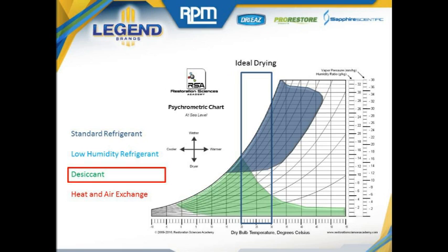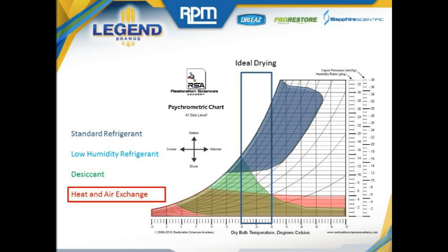In other words, the material that is used to attract water vapor can only carry a certain amount of water vapor at a time. This prevents desiccant dehumidifiers from being highly efficient in higher humidities. In other words, as humidity increases, they do not necessarily increase in performance, and especially as it relates to power consumption, become highly inefficient compared to other technologies in the rate of water removal in high humidity environments.